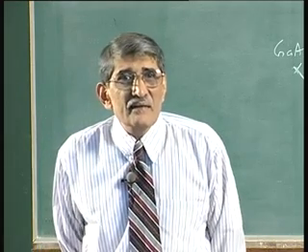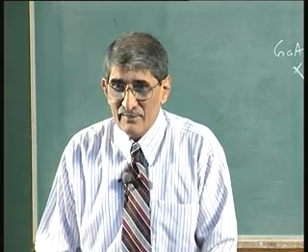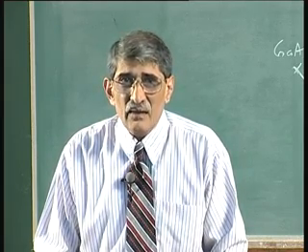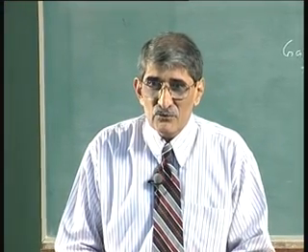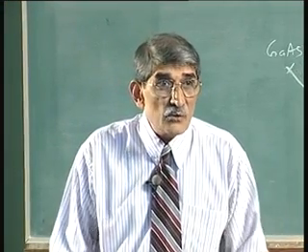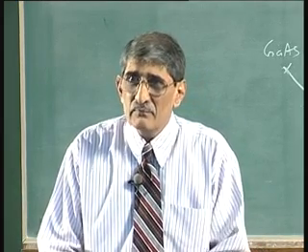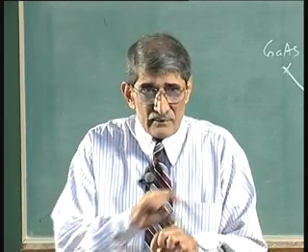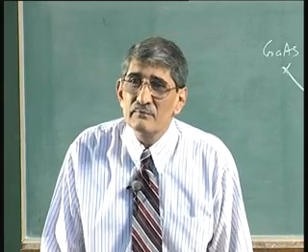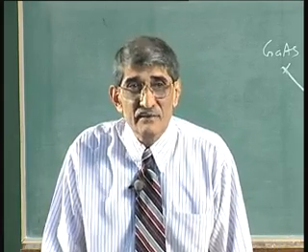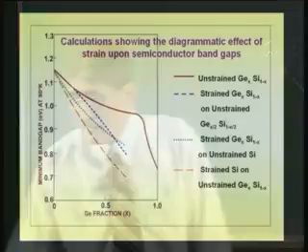Let us take a look at the band gap. There are a number of curves here. All that you have to understand is, if you just have a silicon germanium alloy, you will get some particular band gap, no strain. Just make an alloy of silicon germanium, single crystal, grow a thick layer. The intermediate layer will be defective, but the top layer will be silicon germanium which has no defect, thick layer. That is not suitable for making an HBT, but if you do that, that will be the band gap,